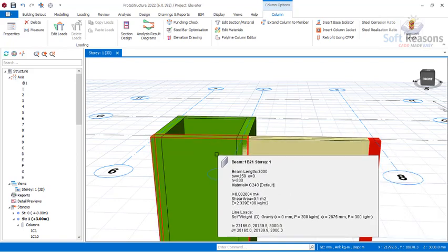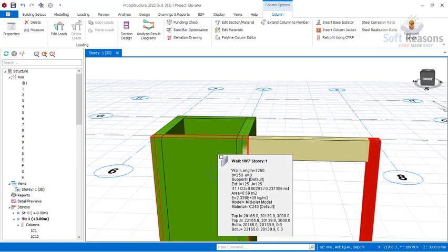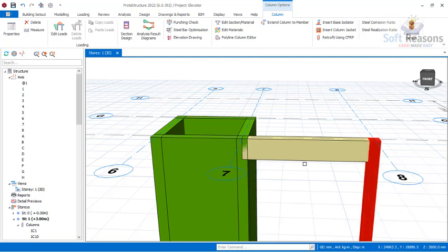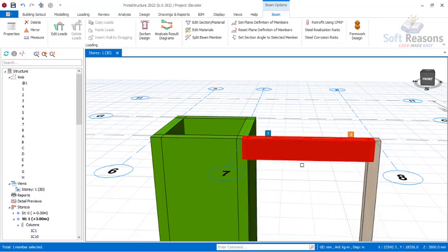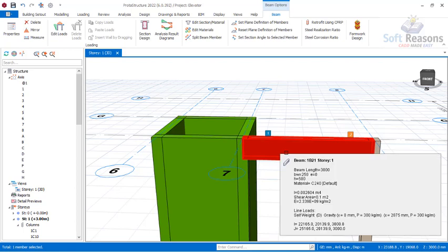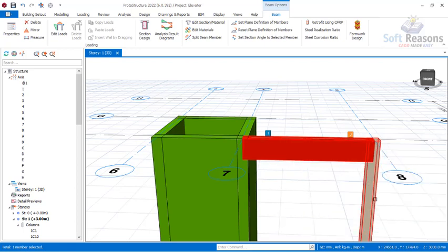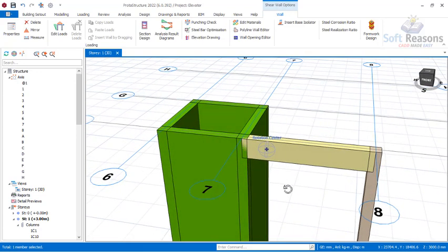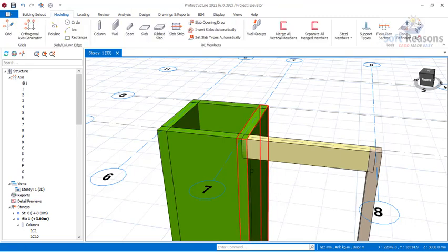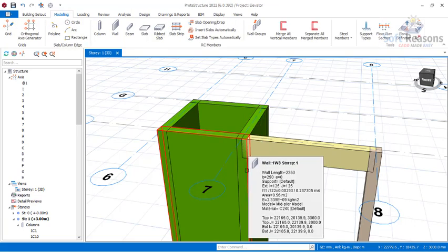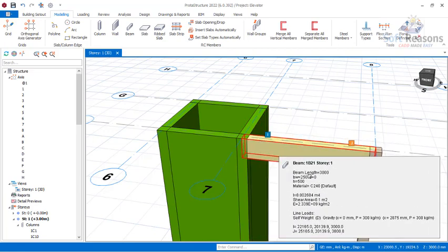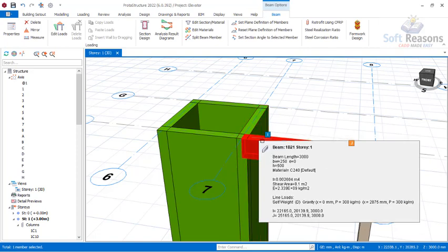If I'm having something of this kind, you can see that this beam is anchored to this wall directly, at my left hand, and anchored to this column at my right hand. You are not supposed to anchor your beam to the wall directly like this, because the load from the slab goes to the beams, and then from the beam it goes to the reinforced concrete column. Likewise, as you anchor it, some part of the load also goes to the wall, and the wall is very low in resisting axial load. It doesn't have enough strength to resist an axial load coming from the beam. That is why I said placing it like this is wrong, so I have to correct this.